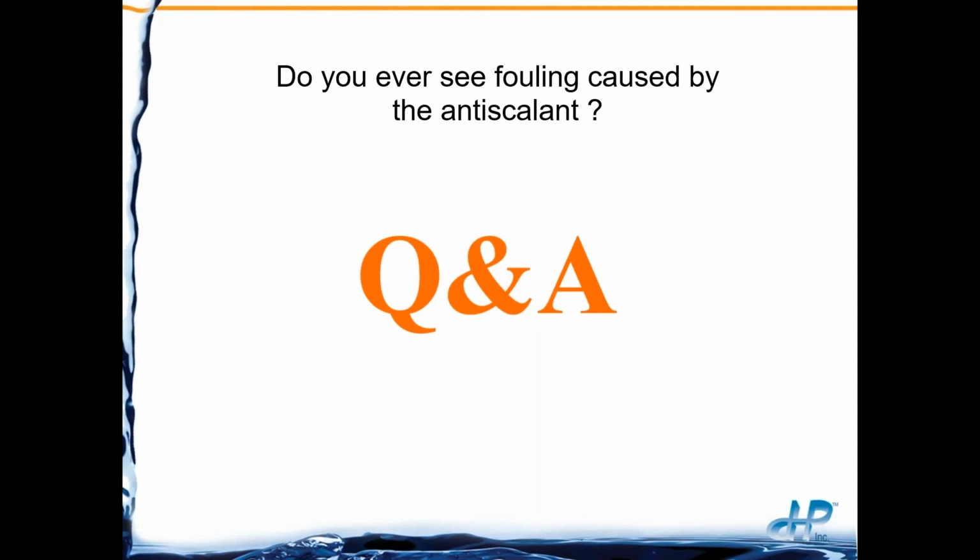We have run into, in the last couple of years though, a scale inhibitor pump that malfunctioned, and while the unit was shut down, the check valves started siphoning scale inhibitor from the day tank directly into the RO system. Scale inhibitor can be a real sticky polymer, so it laid out and did plug up the membrane. That's very uncommon to see.